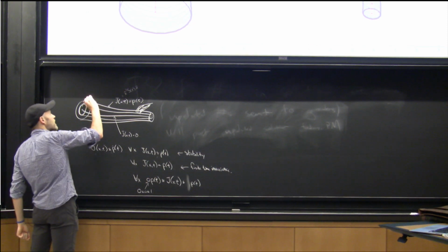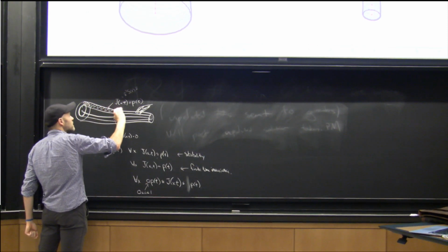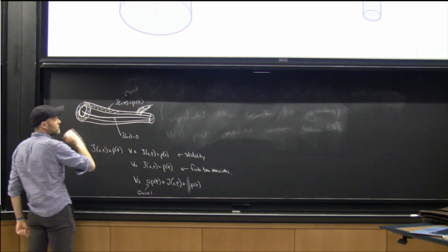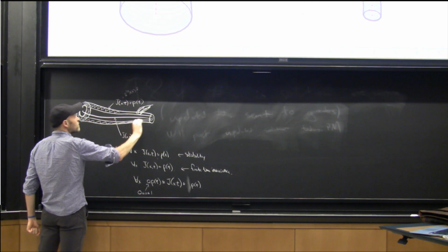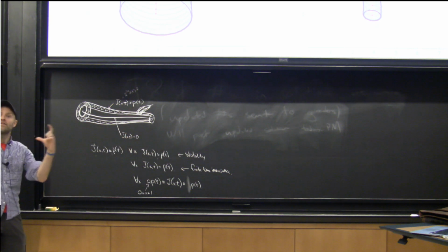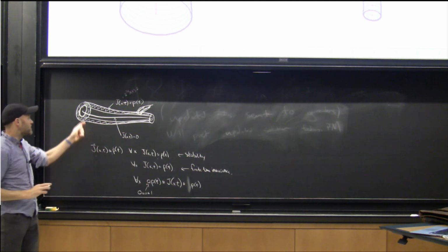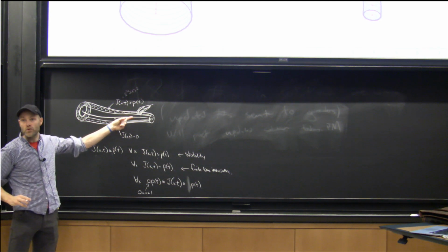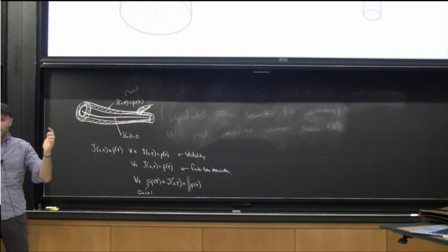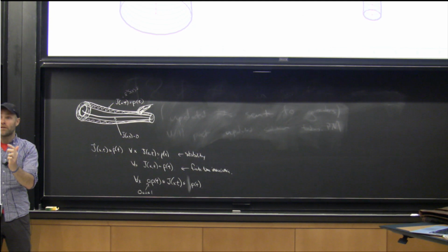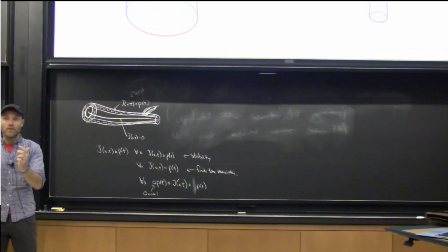So I can try to get a stability property that's valid like in a donut around the trajectory, right, which allows me to shrink to some extent, but doesn't shrink to the point where I get into the numerical tolerance issues of the actual trajectory. So you'd like to say that all sublevel sets between 1 and, let's say, 0.5 are invariant sets. And you can write that down too.